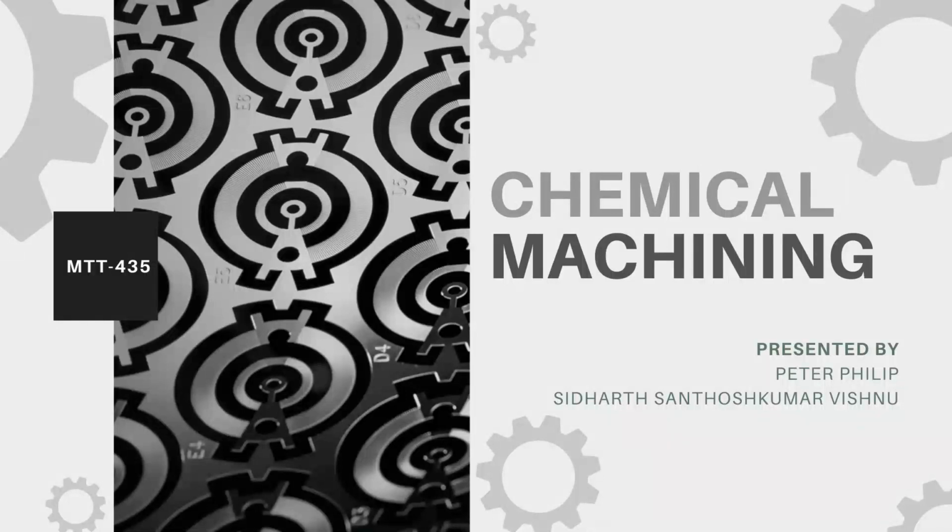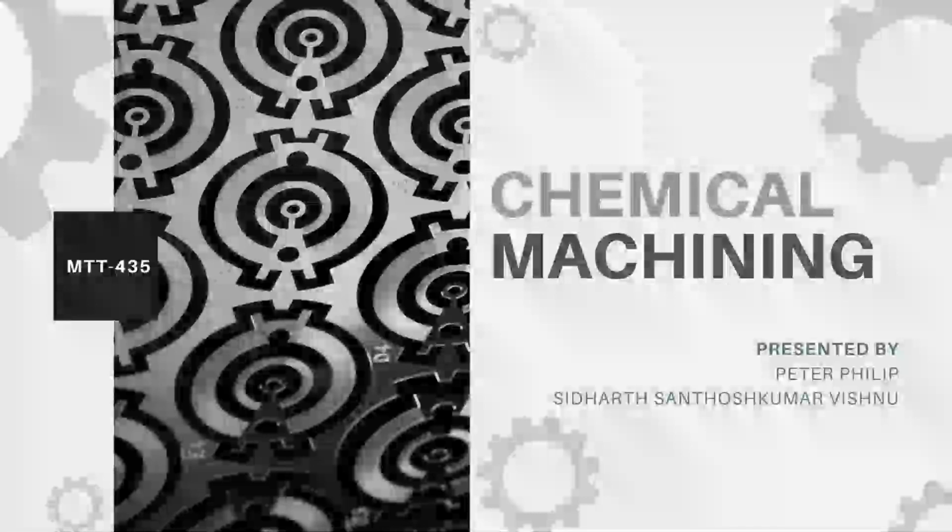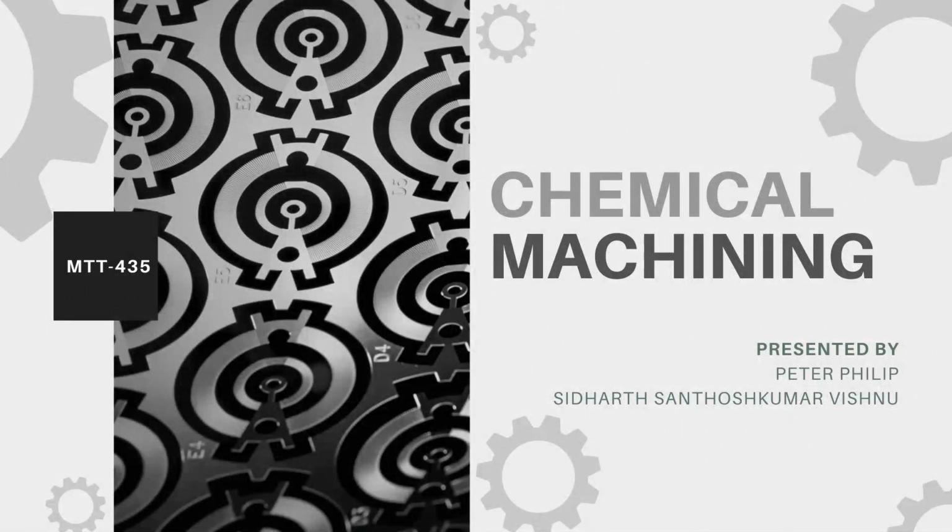So, the machining process can be broadly categorized into two. That is conventional machining and non-conventional machining. Conventional machining includes some common processes such as turning, grinding, milling, etc. Sharp point cutting tools such as a taper tool in a lathe machine, for example, is used for tapering, and they are employed in this technique for machining. And non-conventional machining includes some sophisticated methods such as electron beam machining, electrochemical machining, etc.